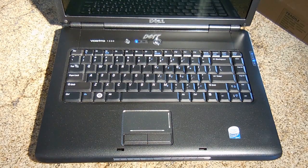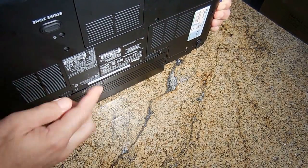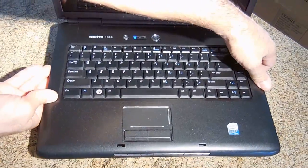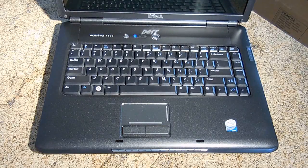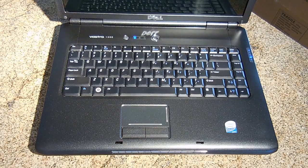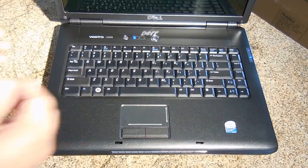You can also take a look at the bottom of the computer. There's a white tag right over here. That's the product ID, the product code, and you can also go to the website for Dell, enter that tag number, and it will give you all the specifics on this laptop. The information that's going to be of importance is pertaining to the display. You want to make sure it says LED, and it does not say CCFL. If it says CCFL, you will not be able to do what I'm about to show you. So make sure it says LED backlight. Now let me show you what you're going to be making.